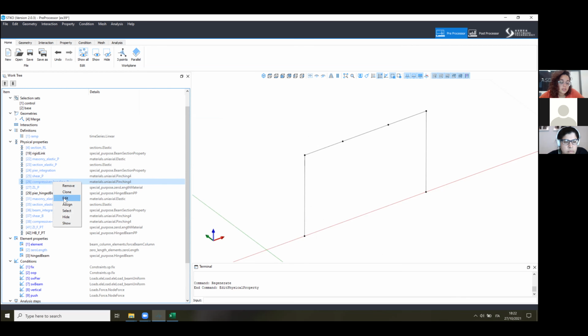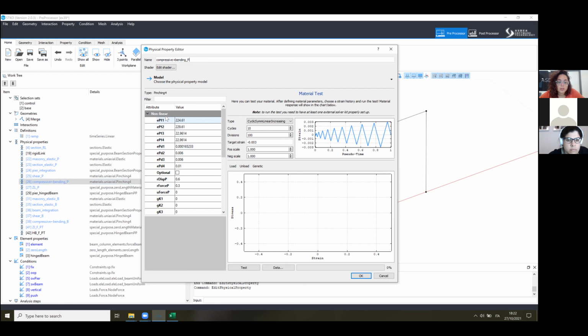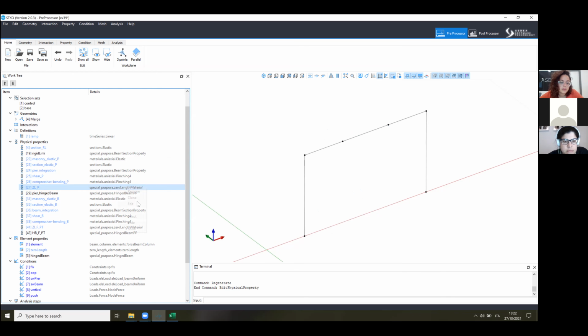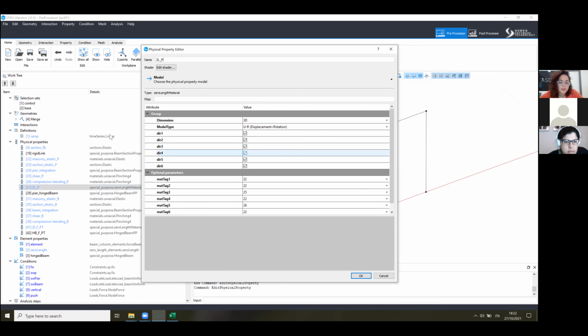And then in this case, we need to model the axial and bending behavior in nonlinear terms, also lumped at the extremities of the element. So to do this, instead of having a shear deformation, we have a shear drift for the shear and a moment rotation for the axial and bending behavior. Then we define a zero-length material and we assign these properties in the right direction.